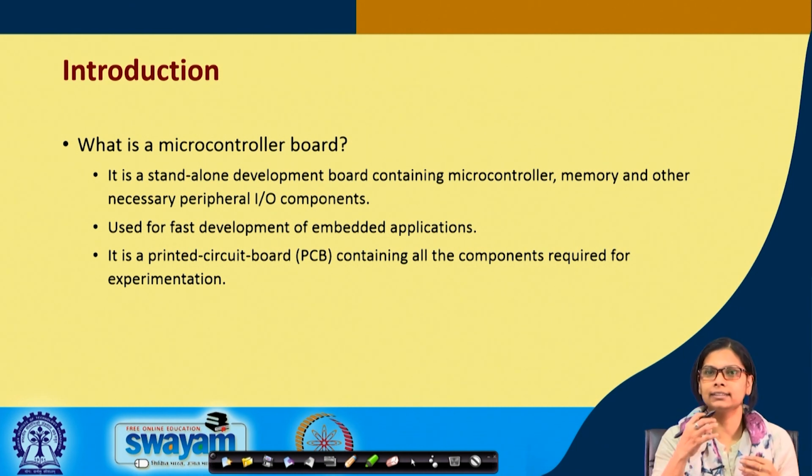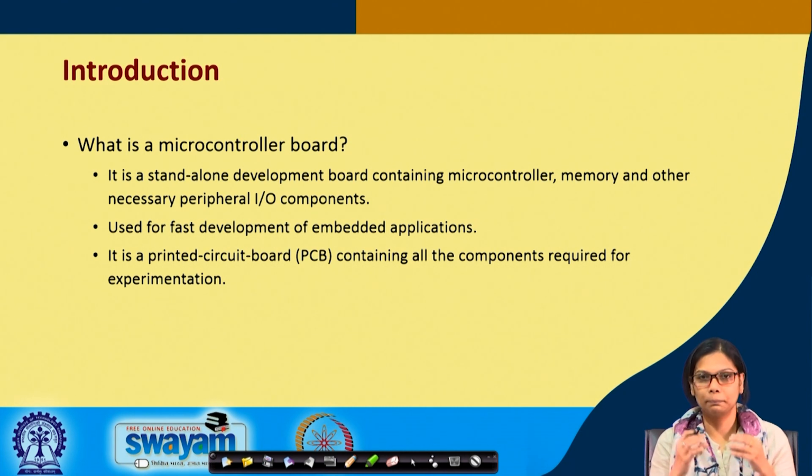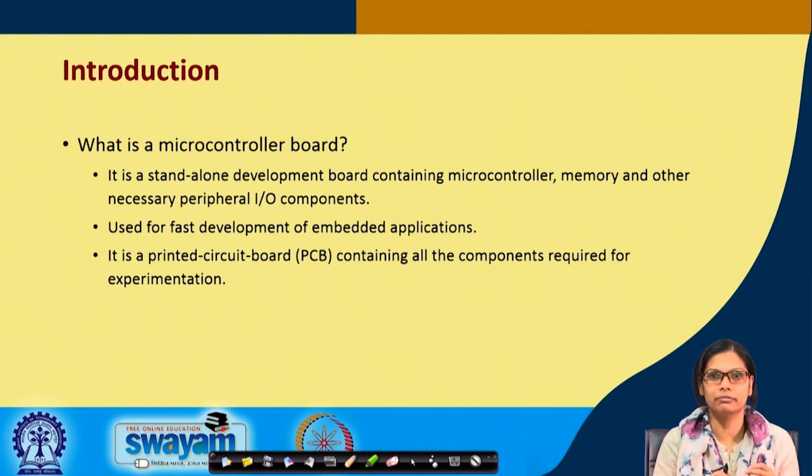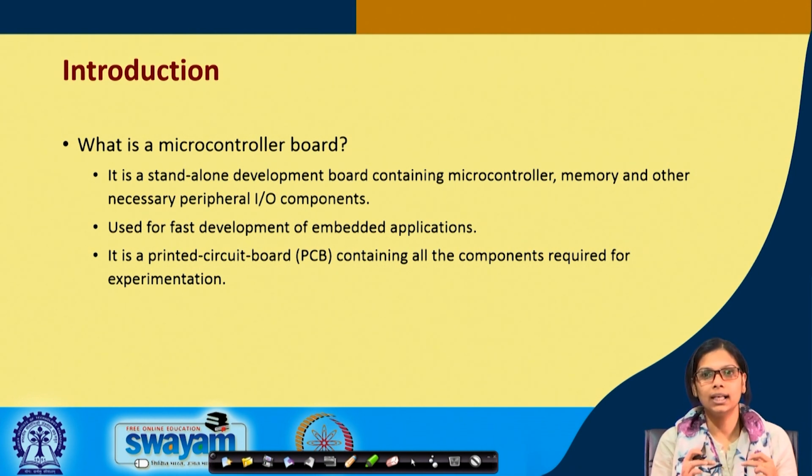You require various other input output devices, but more specifically you need a microcontroller board through which you will be connecting a sensor that will read some analog values, which is in terms of, let us say, smoke inside this room, and it will convert digitally to some value and then will do some kind of operation to find out whether there is a smoke inside this room or not. So, that it will detect.